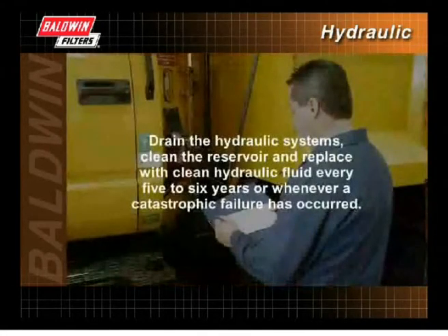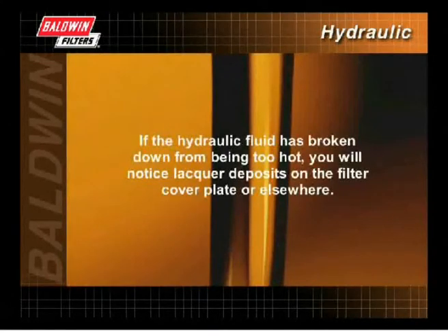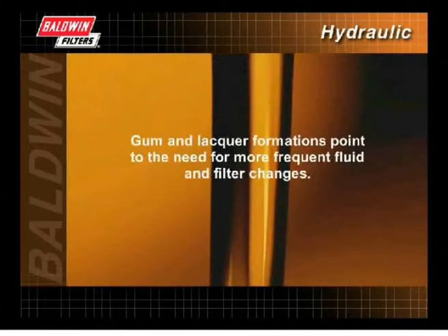Drain the hydraulic systems, clean the reservoir, and replace with clean hydraulic fluid every 5 to 6 years or whenever a catastrophic failure has occurred. If the hydraulic fluid has broken down from being too hot, you will notice lacquer deposits on the filter cover plate or elsewhere. Gum and lacquer formations point to the need for more frequent fluid and filter changes. These formations also indicate a need for flushing.